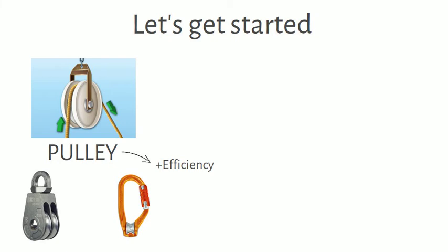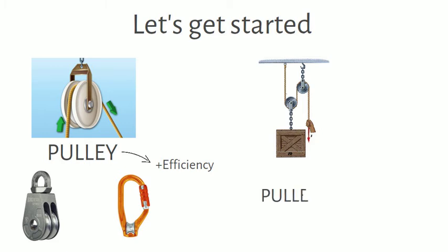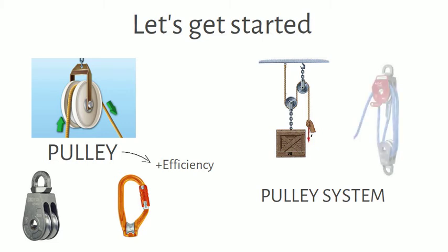A pulley system, on the other hand, is a rope system that multiplies the pulling force on an object through specific configurations of rope passing through the object and through a stationary anchor. The mechanical advantage of a pulley system is solely a function of the rope configuration. A pulley system can function with or without pulleys. However, these are two pictures of efficient pulley systems because they employ pulleys, the piece of gear, at each rope turn to maximize mechanical advantage.